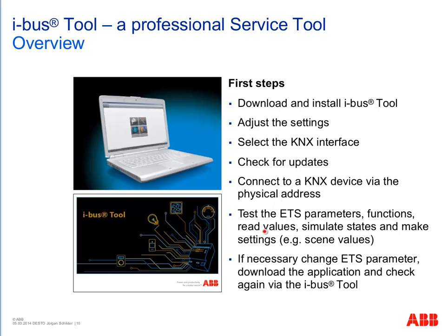Test and check all your parameters and functions, read values, simulate some values, and test the complete KNX device. When necessary, go back to the ETS, change a parameter, download it again, and go back to the IBUS tool and test your new settings. This is the overview of how to work with this IBUS tool.